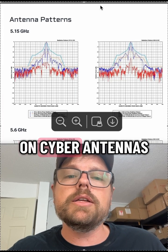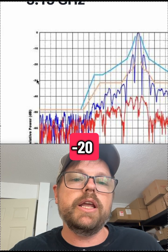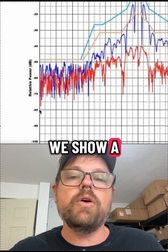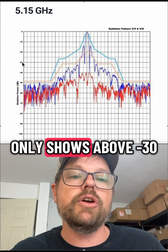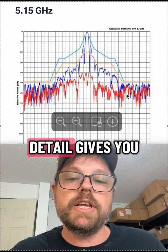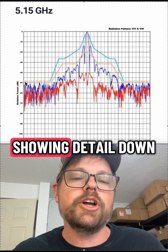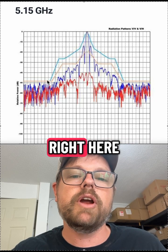On cyber antennas, antenna patterns, we've got 0, negative 10, negative 20, negative 30, negative 40, negative 50, negative 60, negative 70, negative 80. So we show a whole lot more detail in these charts. RF Elements generally only shows above negative 30, so it's just right here. This level of detail gives you obviously a lot more information, but notice you can't even conform to ETSI standards unless you are showing detail down to negative, it looks like negative 48 or so right here.